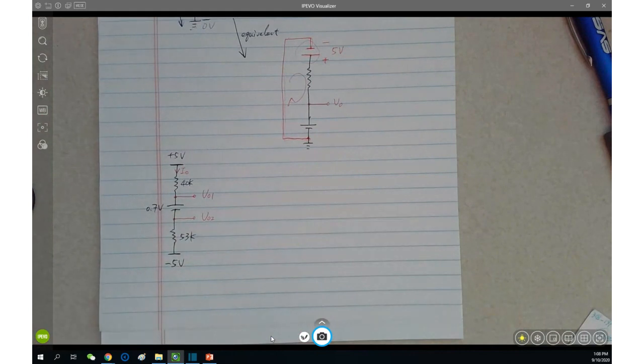So now I'll give you guys about 5 minutes to try this over yourself. Go as far as you can and follow the pass KVL idea to come up with some equations. Let's see where you can reach. There are 3 unknowns to be found: I naught, V naught 1, and V naught 2. I will present the solution in around 5 minutes.